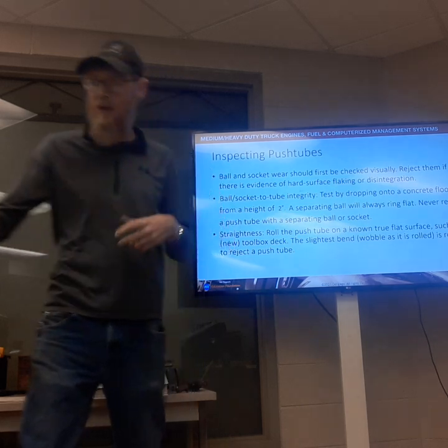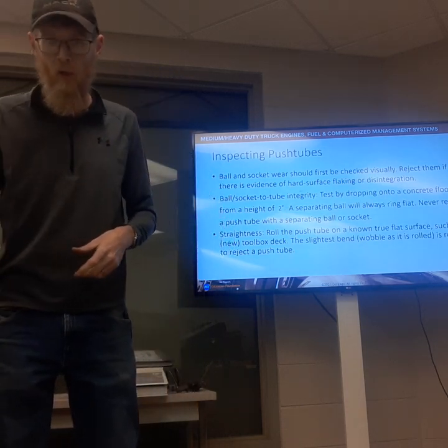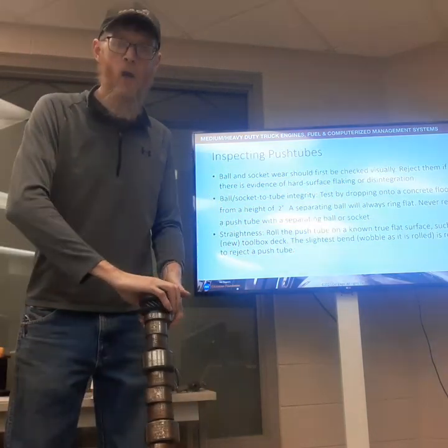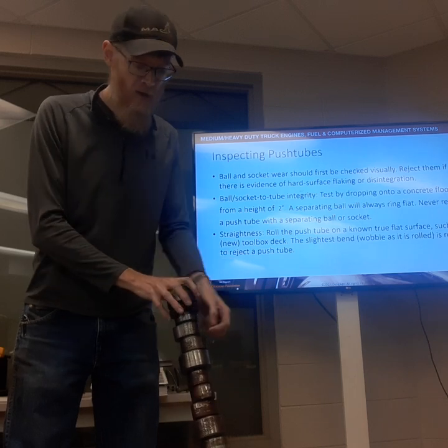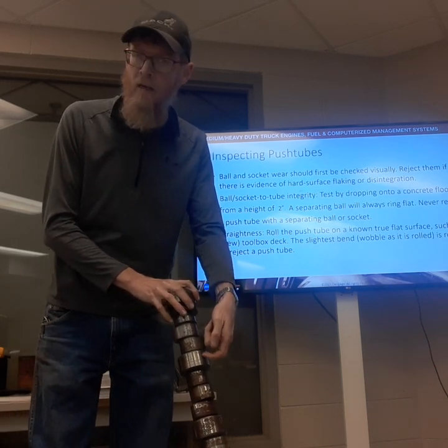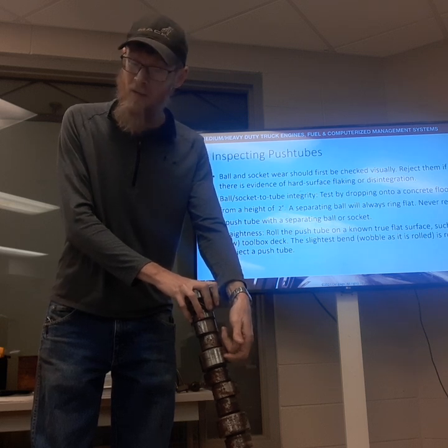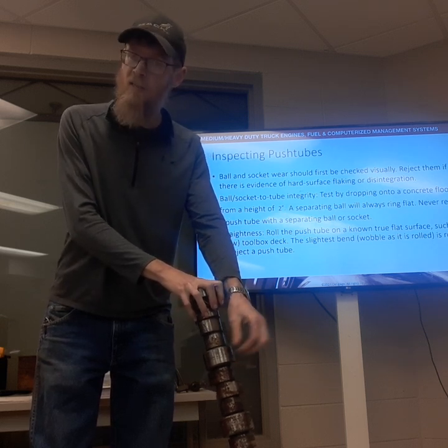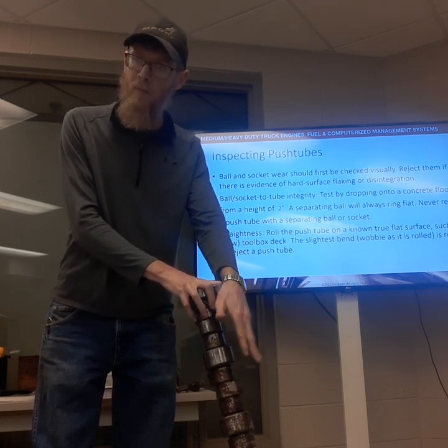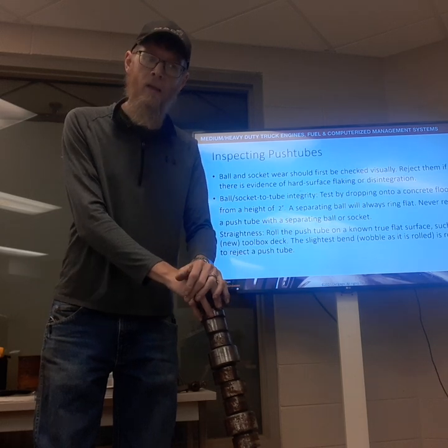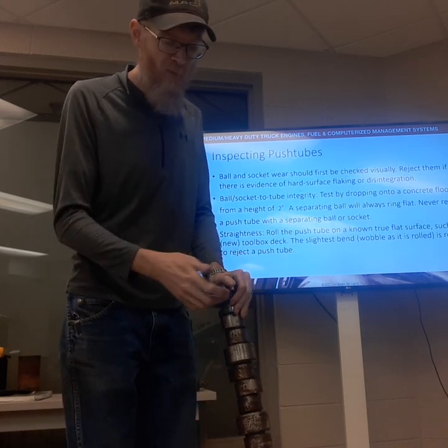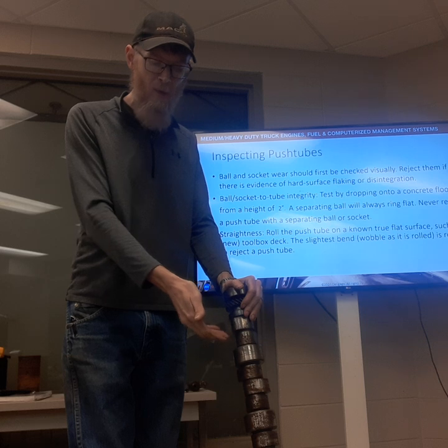If we were to inspect a camshaft and are looking at the cam lobes, I don't know how well you guys can see this camshaft I've got here, but there shouldn't be anything on these surfaces that can catch your fingernail. If there is, then that surface is excessively worn, and that problem needs to be addressed rather quickly. It's going to hurt engine performance, especially if we have wear on a cam lobe.